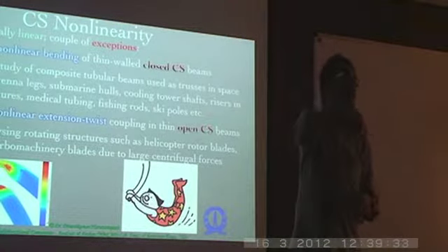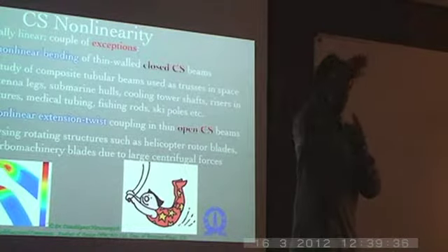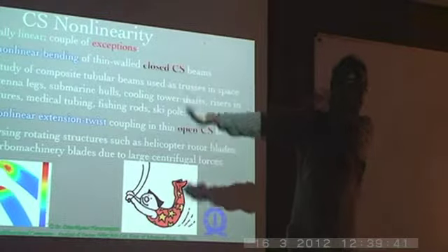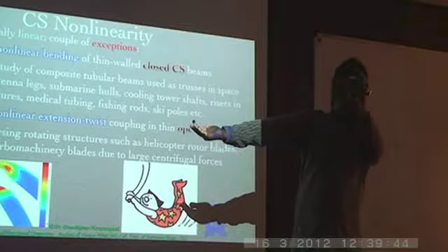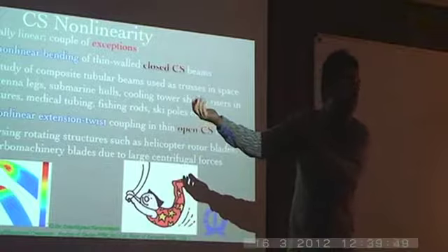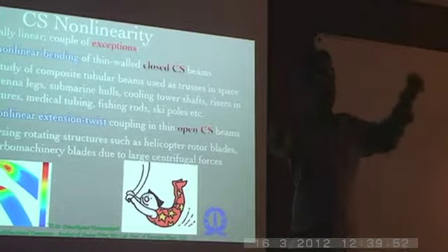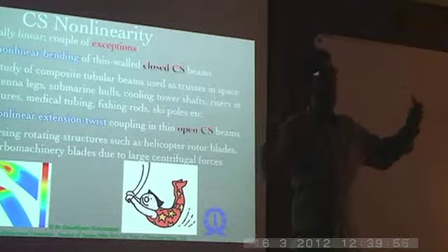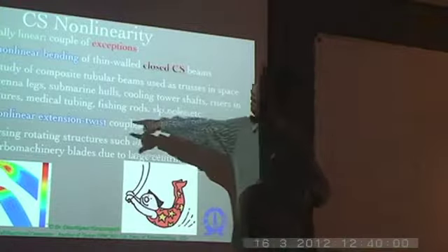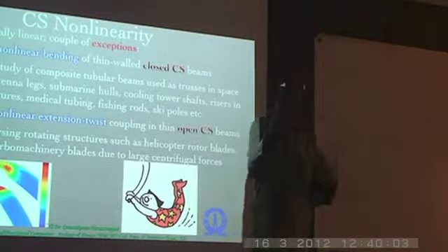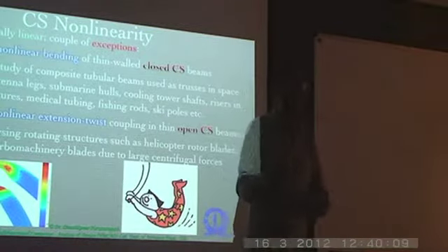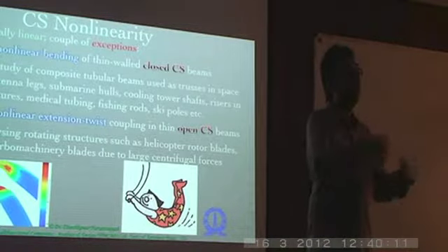But the way this moment is distributed here is such that you have axial loads, that is axial tensile and axial compressive loads. For example, when the wing is bending like this, all the stringers on the top surface are undergoing compression, and on the bottom surface they are undergoing tension. So it's not actually a bending which is happening. They are just tensile loads which are happening. Now if there is a combination of that tensile and some torsion which is also there, then this kind of an effect can come into picture. So it all depends on a case-by-case thing, and also the relative magnitudes of these various loads, the geometry, the material properties, all of these come into significance.